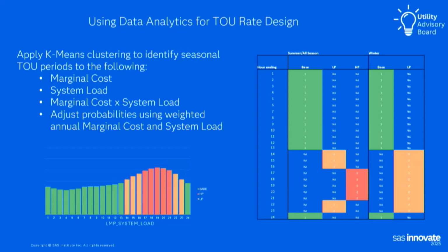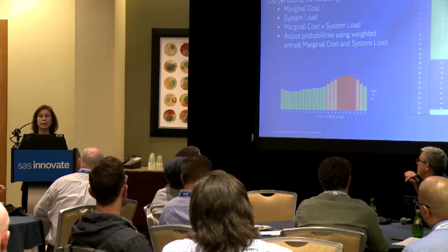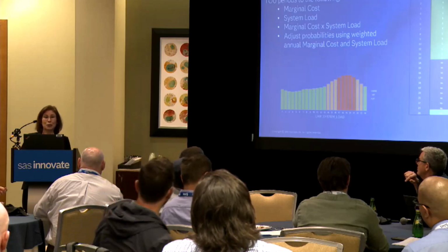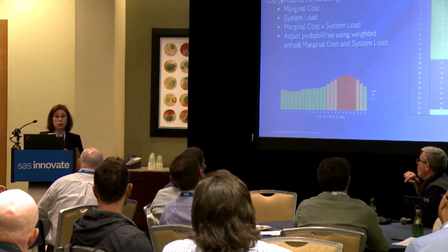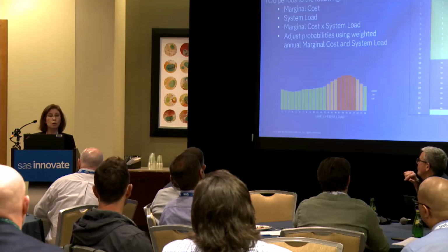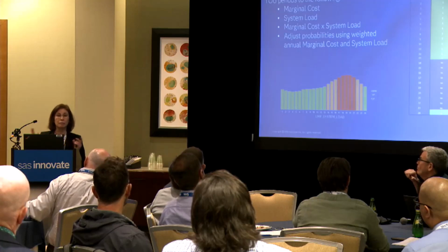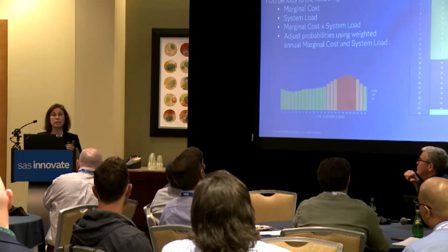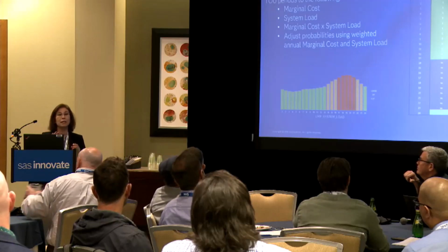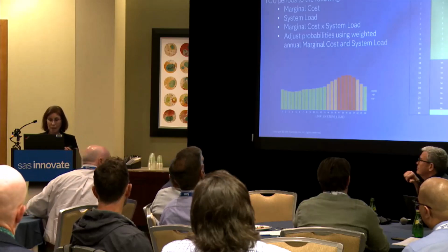Now keep in mind that within LADWP, since we don't have a huge solar penetration within the city, we don't have that severe duck curve yet. So as more and more customers start coming in, we'll probably start seeing it. And we've seen it transition over the years, but it's still not where we're going into the negative or seeing that big dip, especially in the wintertime. During the summer, when everybody's using air conditioning load, you barely see it at all. And then during the winter, you see a very slight dip, but nothing significant as a lot of utilities are now seeing.